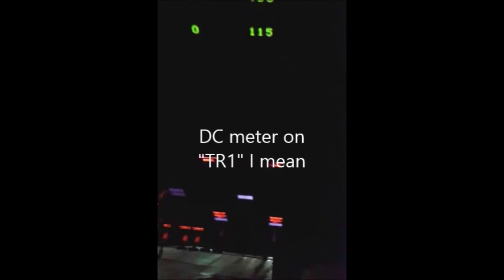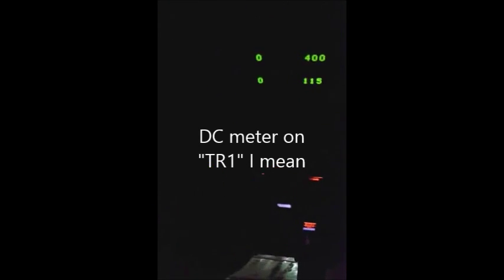Turning off ground power is just as easy as turning on. All we gotta do is move the momentary switch back. Make sure the battery is on TR1. And turn off the battery. That's it.